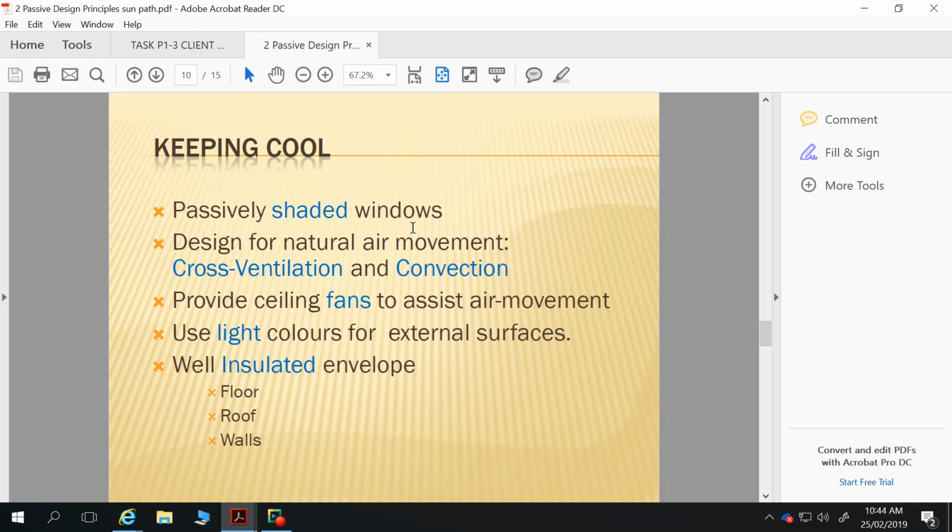Then beyond that, another aspect we have to think about is insulation. So insulation, well, there are limits to insulation. Insulation needs to have space. If we get an R4.5 batt about this thick, and we go, oh, we've only got this much room to put it in, let's squash it down, that R4.5 batt suddenly becomes like an R2.5 or R3.